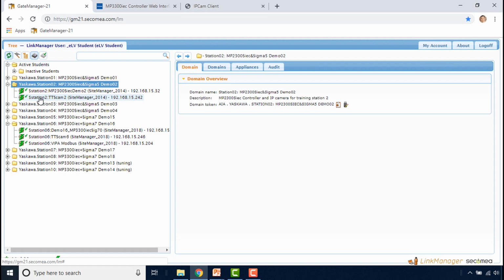But even if you do find the same station open, remember another user could have used that station and changed its configuration while you were away. So please save your data before you disconnect. And when you return, remember to restore the configuration, the servo parameters, the programs before you proceed.